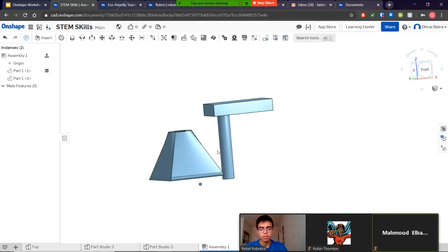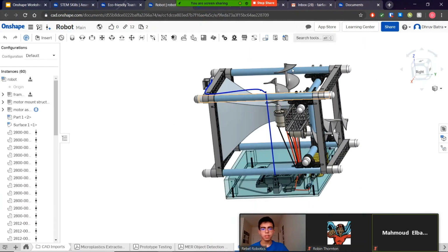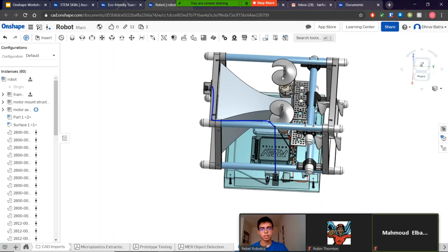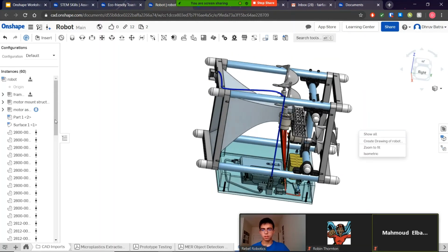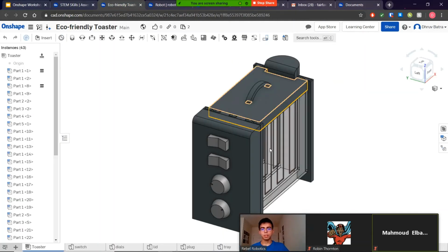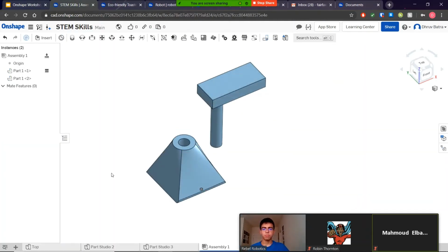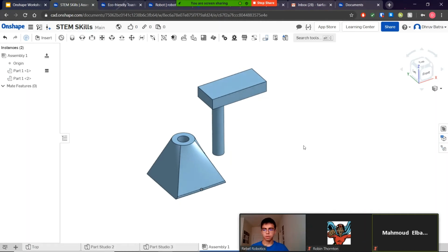What a CAD assembly is, in some cases, is a simulation, right? So for example, if I go here, I can twist the propellers. Like I can move the propellers, right? Here it's lagged a bit, but you can see it. So it's a simulation of sorts, and in a simulation, you want to make sure at least one thing is fixed. That way, all your other features or mates are relative to that fixed object.